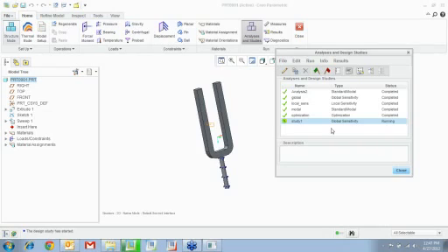So let's say at 235,000 I get my optimum value where the stress and displacement and everything is under control. Then I can say, hey, let's find out a grade of steel that has 235 and we can use that for this particular part.